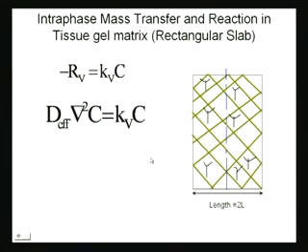So, once you assume a pseudo homogeneous model, what does it come with? The other assumption that diffusion and reaction can run parallelly. Okay. So, in reality, what is the difference? This model that you are writing tries to mimic reality, but is not a direct actual representation of reality. It's some sort of deformed representation of reality. So, in reality, diffusion and reaction do not occur parallelly, they occur in series, but when you convert them into a pseudo homogeneous model, diffusion and reaction can be assumed to occur parallelly.